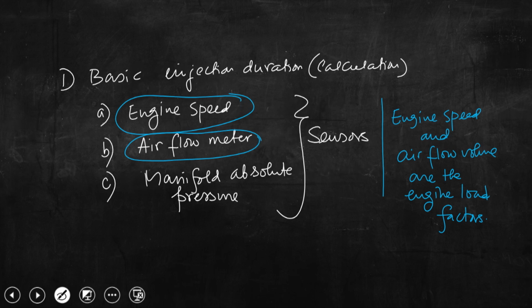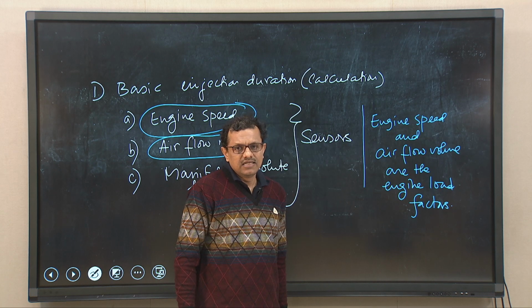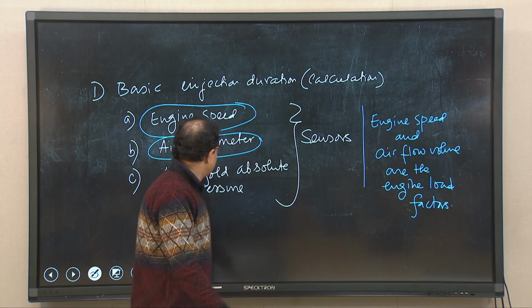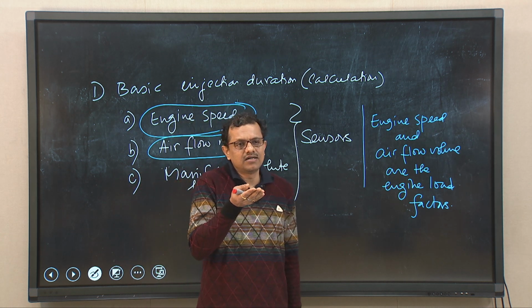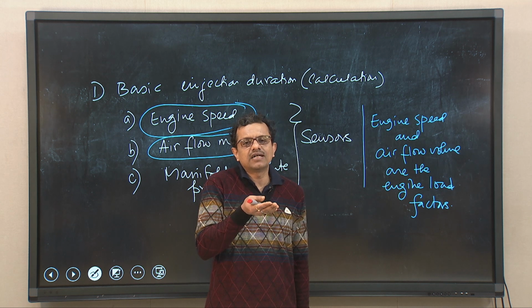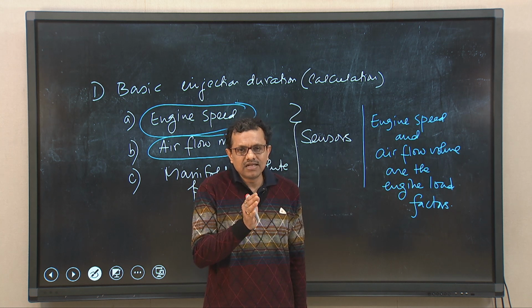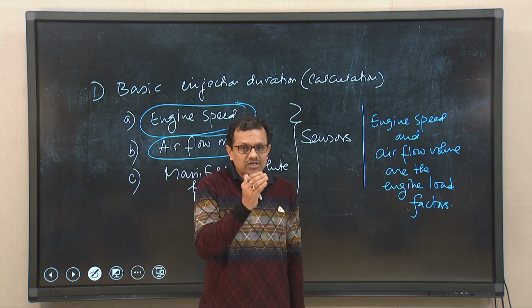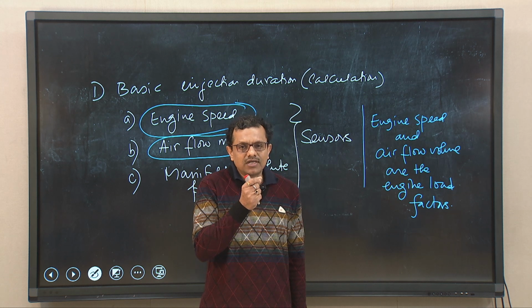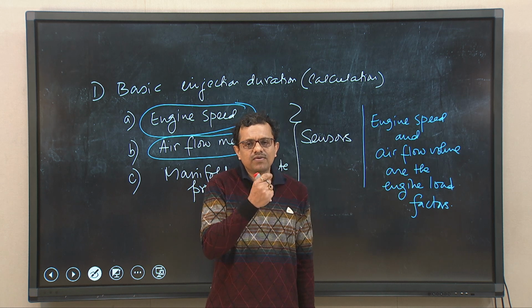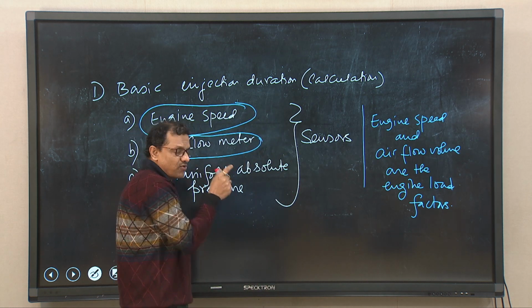Now, if either of these two parameters increases, basic injection duration is increased. Quite obviously, if engine speed increases, the fuel that needs to be supplied to the cylinder should increase. Similarly, to meet the load of the engine, if the engine needs to develop more power, if we need to extract more power from the engine, airflow volume should be more.